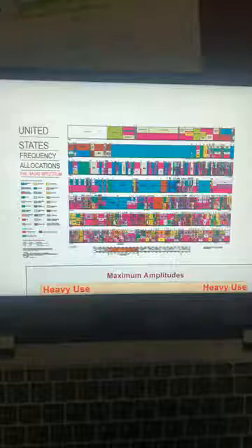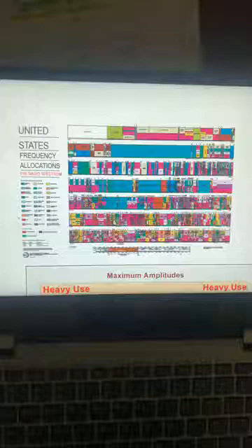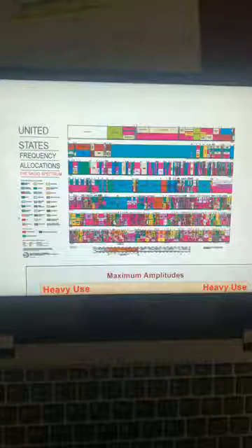And for analyzing, all the time you're taking FFTs. There is equipment which looks in the sky and all the time takes FFTs to show you which part of the spectrum is occupied. And if there is a part of the spectrum where there should not be a signal and somebody is transmitting, you immediately figure out that this is an illegal transmission.